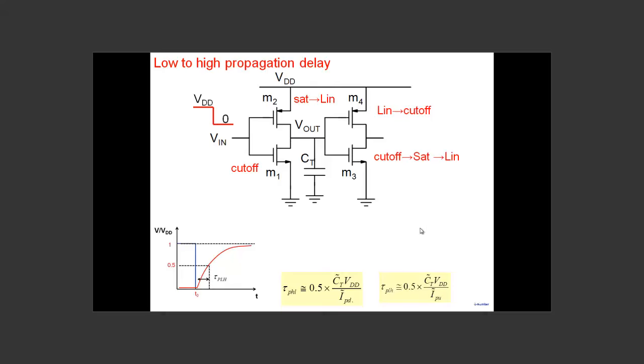All right, so all these are making transitions. All these transistors are, except for this one, which becomes, let's say, cutoff. The transistors are changing states. The voltage at this particular node obviously is changing. And if the voltage at this node is changing, the voltage at this node is also changing, because if this is switching, then this will cause the second inverter to switch also. Right? So all these things are changing.